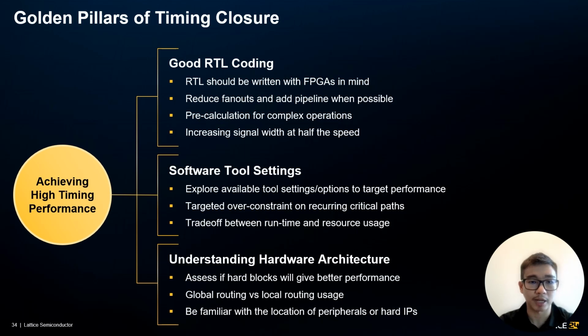Finally, it is highly advisable for designers to understand the hardware architecture of the targeted devices. Hard blocks such as RAMs and DSPs are dedicated resources with high efficiency, so that should be considered. The same goes to the location of peripherals and hard IPs because these have fixed locations. Therefore, it is not advisable to have critical signals having long routing delay to these blocks.